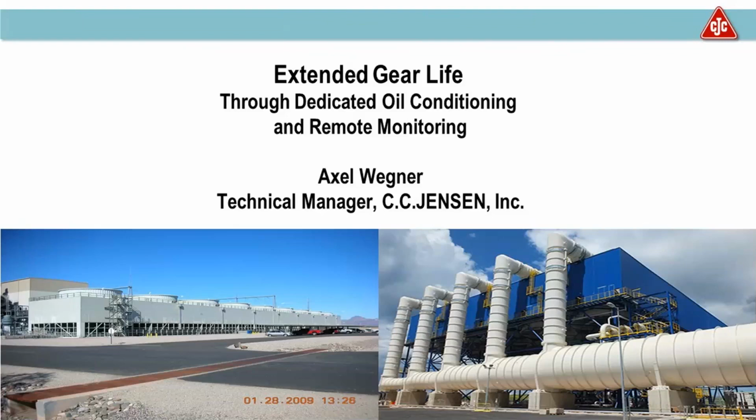Yes. Okay. So basically, you have something like a sawtooth cleanliness curve if you do it with a mobile unit that you move from gearbox to gearbox. And that is actually how many of the ACC gearboxes are being maintained by some of our customers now. They have some mobile filter units that they move around.